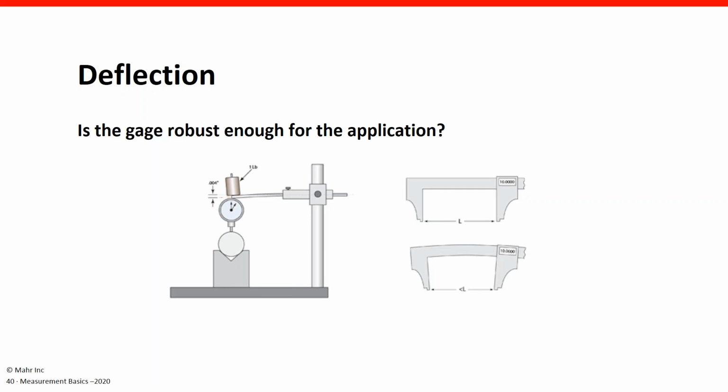And even with a caliper or micrometer sometimes, because they're influenced by the operator, not every operator has the same gauging force that is used with that instrument. So a person with a pretty strong thumb might be deflecting the instrument and causing a little offset in the readings. So deflection is built into everything, but you can control that by knowing the forces and building a good, stable gauging station.